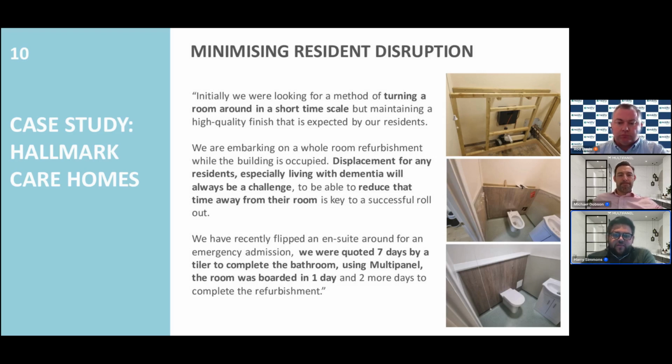So for instance, this room, it's not the room pictured, it's one on the next slide actually. There's about 7 to 8 panels for the bathroom, and that was installed in a day. So if you're just doing just the wet area, say 2-3 panels, you're looking at a couple of hours for installing. And then you've got to wait a few hours for the adhesive to go off, and you can start drilling into it and fitting all your other fixtures in the bathroom. So it's really that quick.